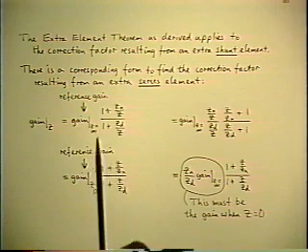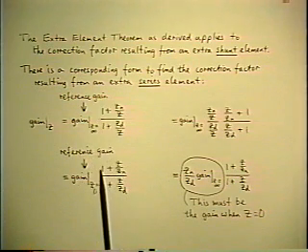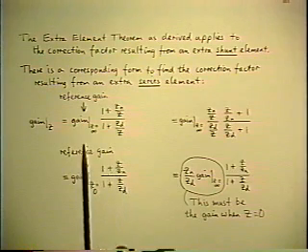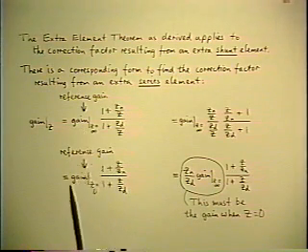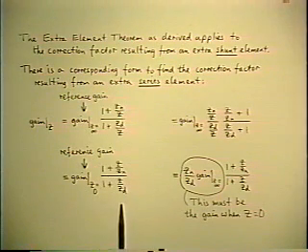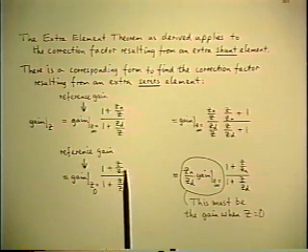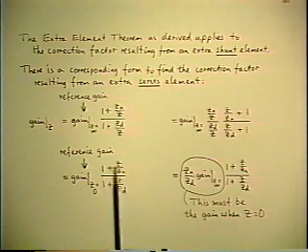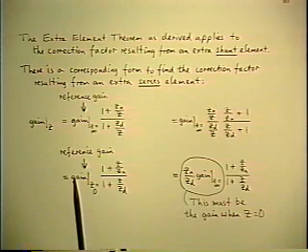And I pointed out at the time that this was a direct analogy with frequency response. You could either use the zero frequency gain as reference or the infinite frequency gain as reference, and you have either a normal pole and zero or an inverted pole and zero, and this is exactly the same thing except the variable is impedance instead of frequency.